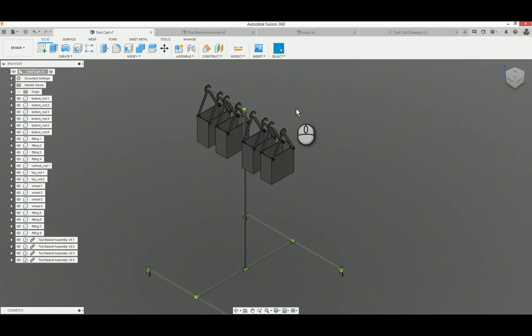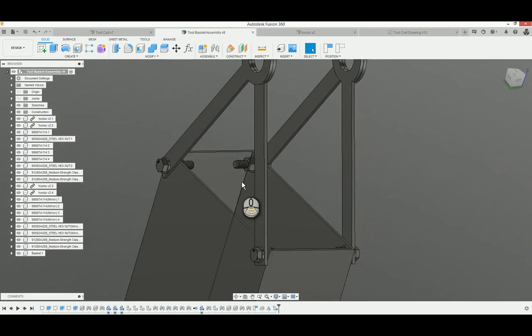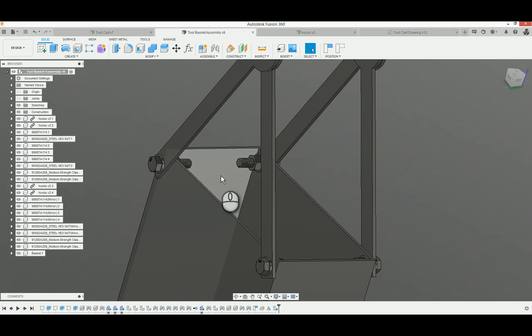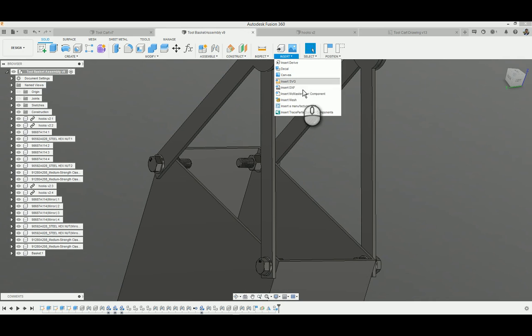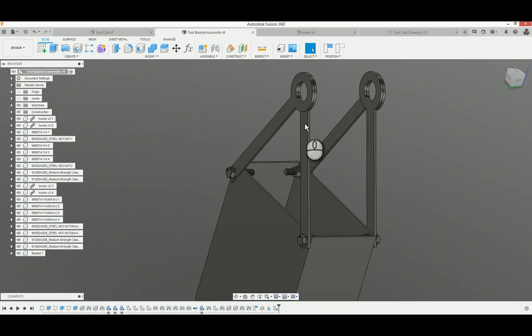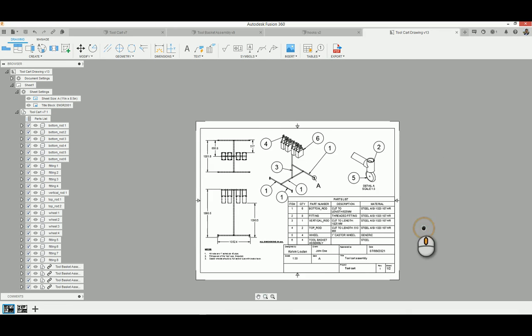Right, so in terms of the drawing, after you generate your 3D CAD model, this here is the basket assembly by itself. We see we had some nuts and bolts. In SolidWorks you would have similar insert component options just like this. So you could insert a component such as a nut or bolt from different manufacturers. You just need to play around with SolidWorks and do some online searches, and it's very simple. In Fusion, as I said, it's not so simple, and in SolidWorks it is a lot simpler. So this is generally how the drawing is supposed to look.